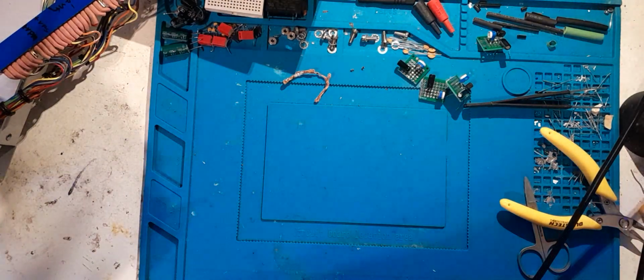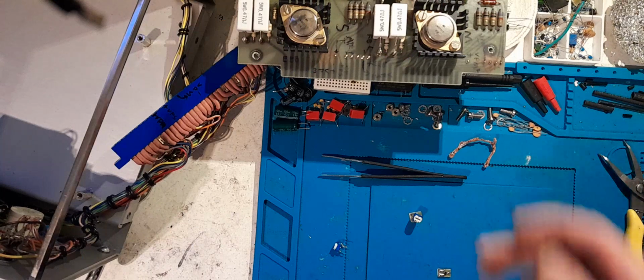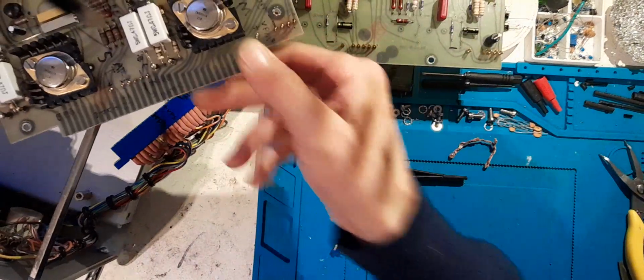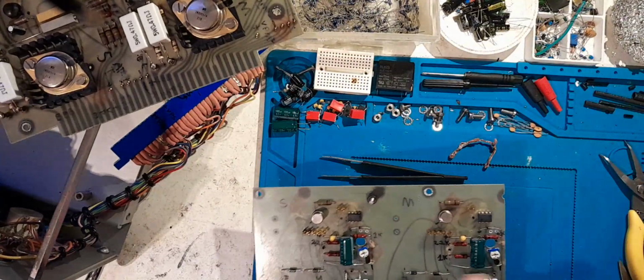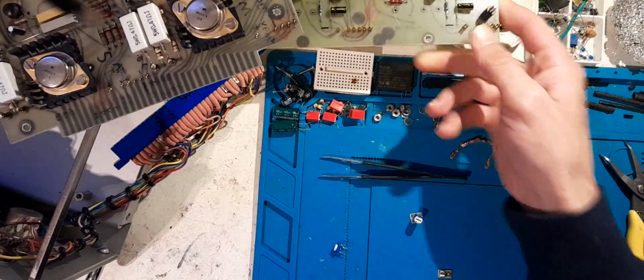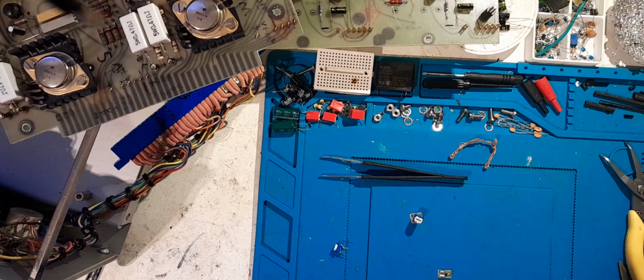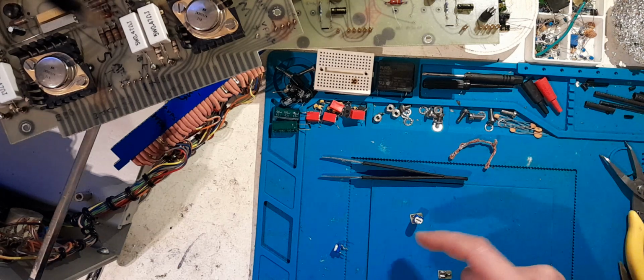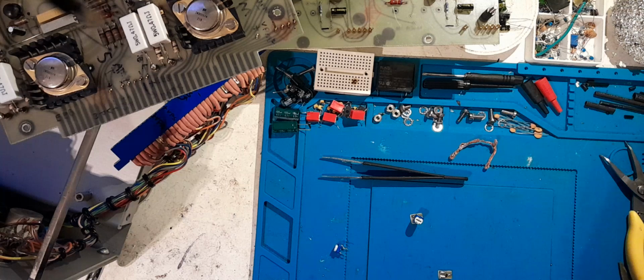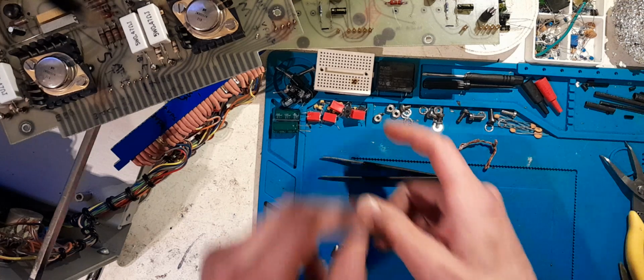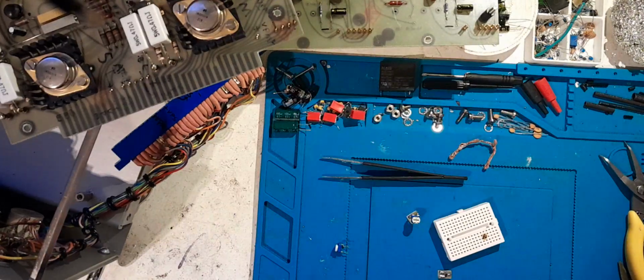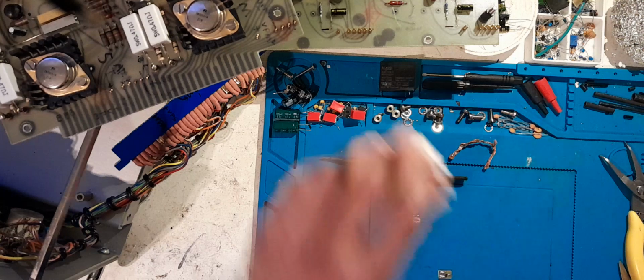I'll be back soon. Right, so moving along, I got both of these dialed into 5.1 volts. That other reference, I blew it when I tried to power it up with one pin unsoldered. That happened to be the reference pin. No, the reference pin was connected to the pot, but only one side of the pot was connected to the rail, so the whole positive voltage went in the reference pin and cooked it. So I then stuck it in my breadboard and had some fun with it. Probably shouldn't have done that because now my breadboard's messed up, but whatever.